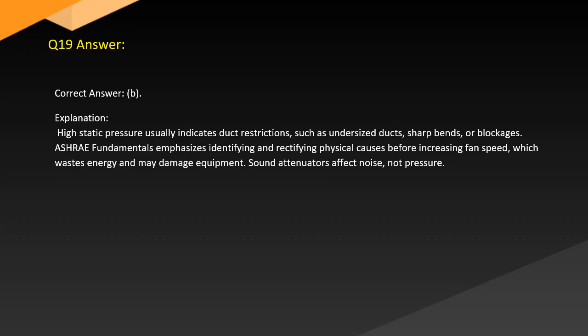Answer. Correct answer, B. Explanation. High static pressure usually indicates duct restrictions such as undersized ducts, sharp bends, or blockages. HRConquer Fundamentals emphasizes identifying and rectifying physical causes before increasing fan speed, which wastes energy and may damage equipment. Sound attenuators affect noise, not pressure.